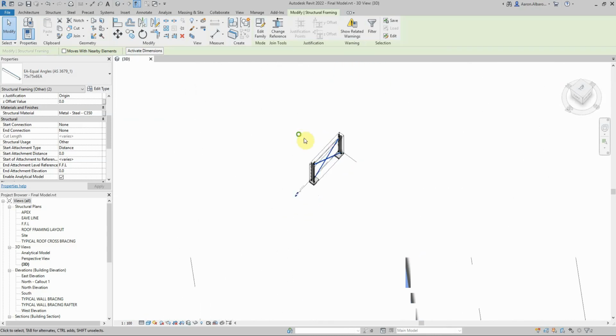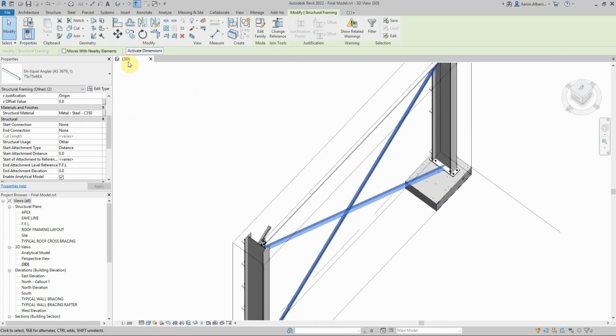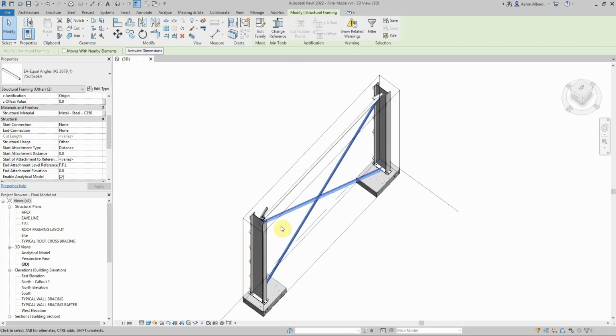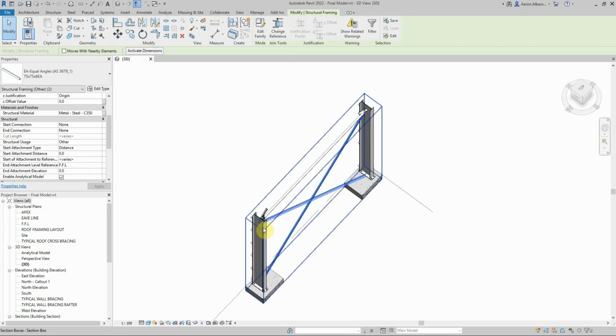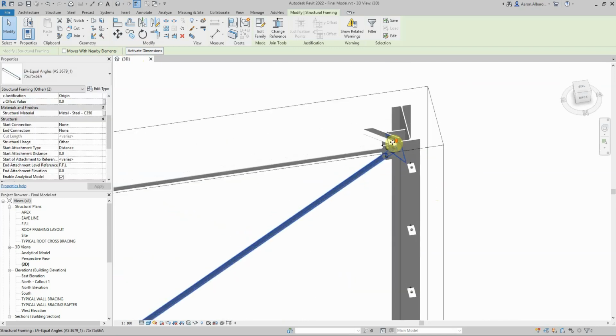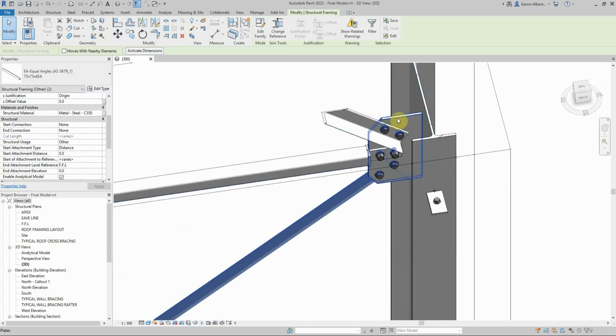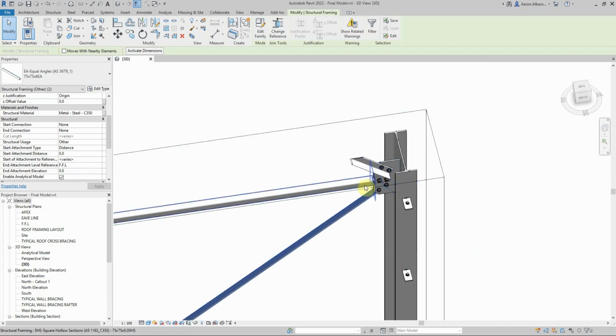Alright guys, so I'll leave that with you. Could you please, on your model, do all the connections as we agreed. This type of connection here, by doing this type of connection, before you break the connection, if you right click and propagate, that will propagate this connection for all similar locations. So could you please on your model do the connections for all wall and roof bracing.